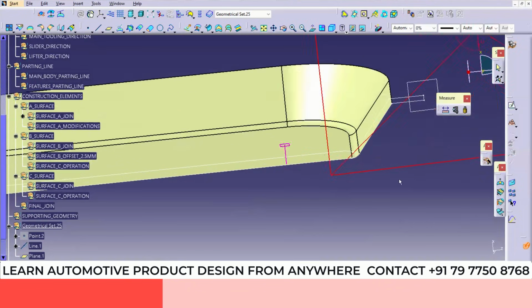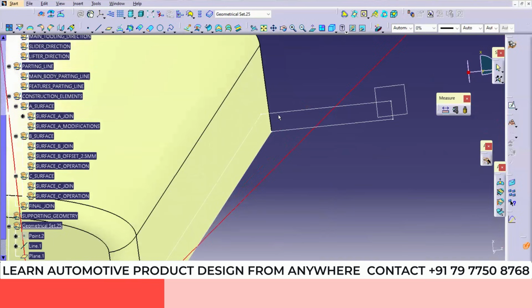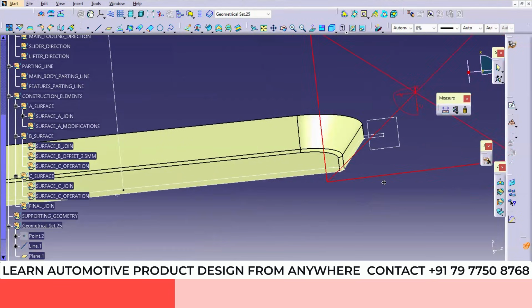Bottom line is following the class A surface till here, till this point. Then here the surface is not there, but the line is continuing, meaning the master section is there till here, right? But no surface, so this surface we are going to generate from the class A surface. Then next is the offset surface. So this is the offset, this is the offset. These are all the offsets, meaning B surfaces. And this line belongs to the C surface, which is joining class A and class B. Okay, we are going to follow the same.